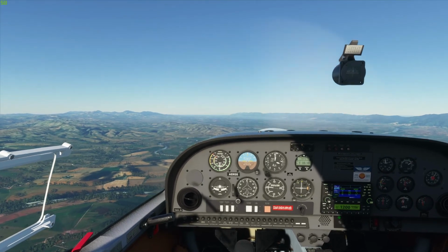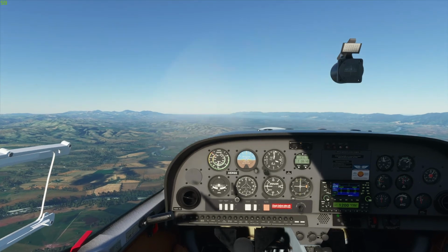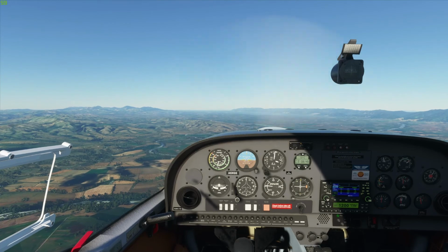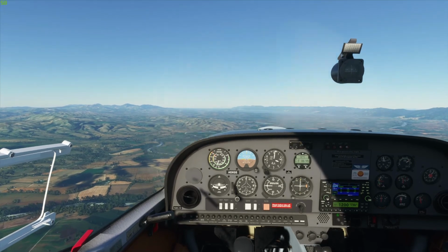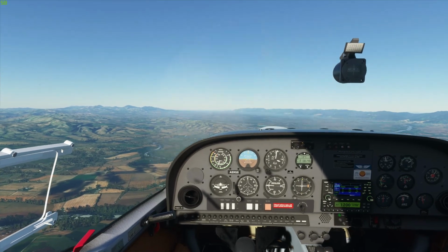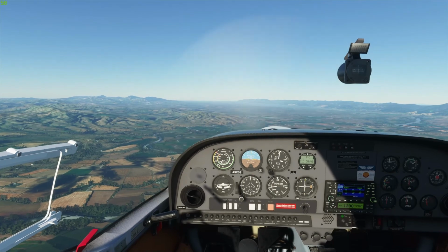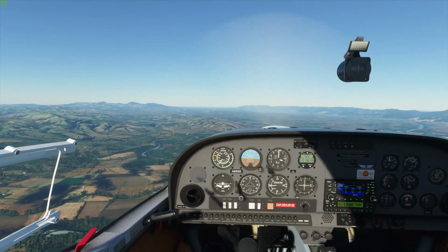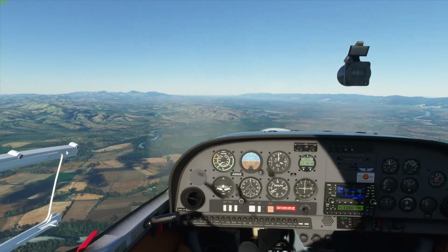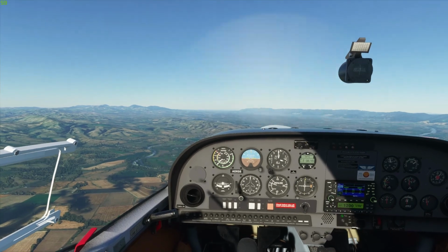So now I'm just driving for level flight. No trim yet, and I'm just holding the stick pressure nose down to allow the aeroplane to accelerate, and I'm just going to introduce a bit of nose down trim there, and as I do so I'm progressively increasing nose down trim and reducing the forward stick, just trying to find that balance. And I'd expect it should cruise around 105, 110 knots.